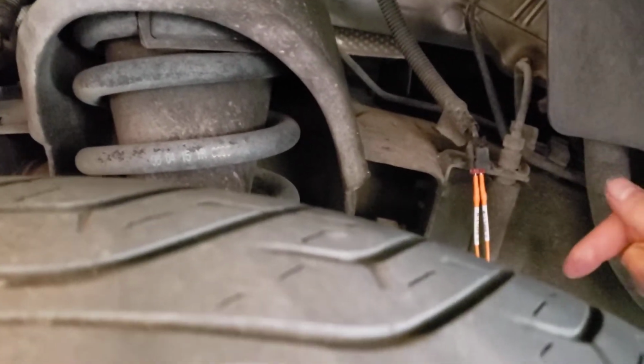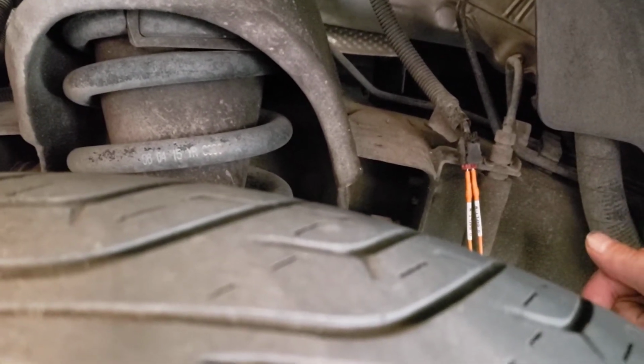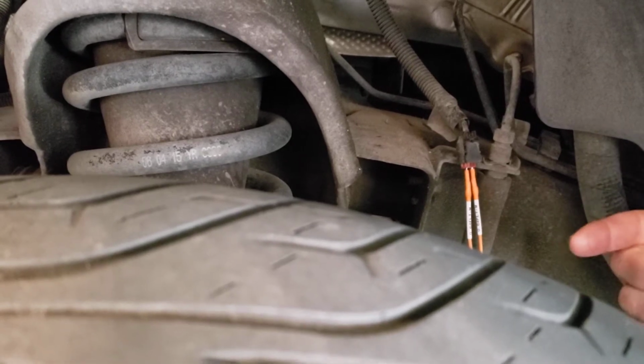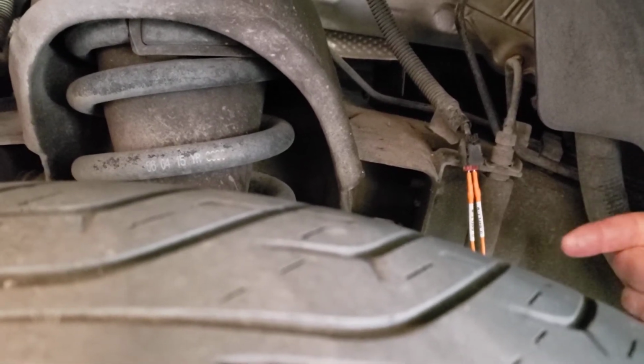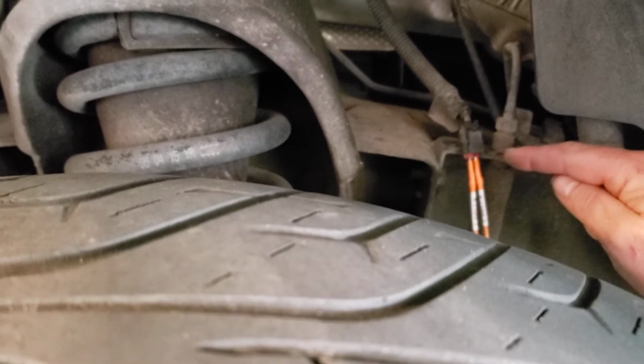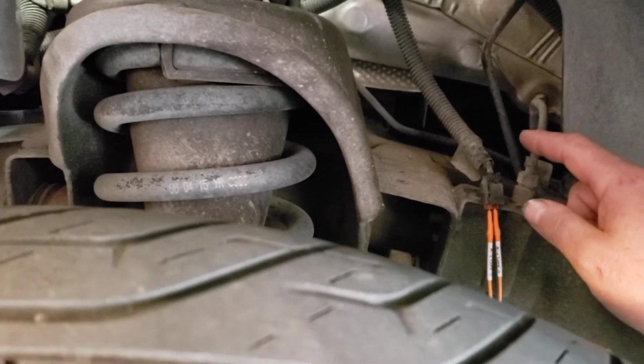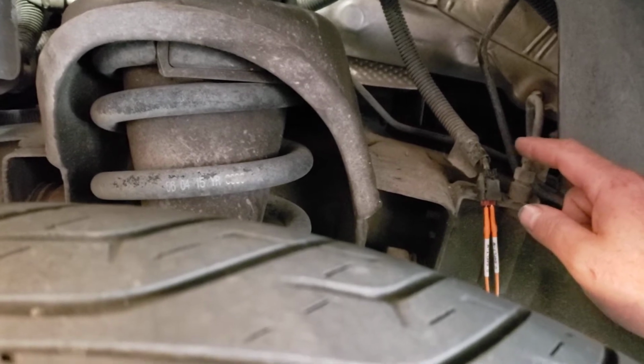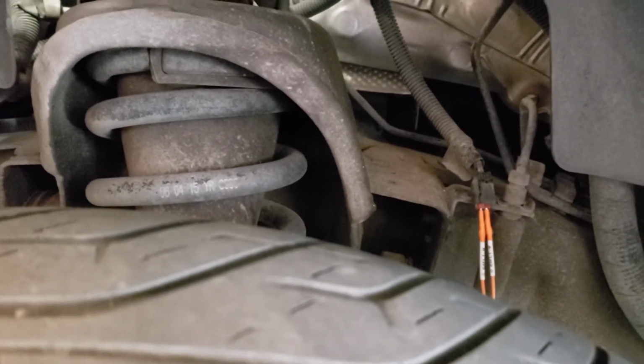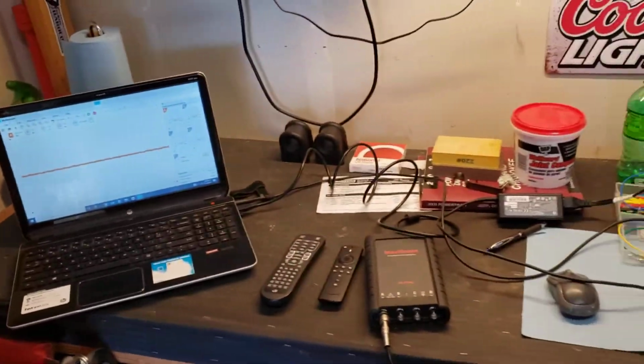Why would you want to use this test? Well, say a suspected bad wheel bearing, say that wasn't the issue, but there's a wiring issue from the connector to the harness through other connectors to the electronic brake control module, we could introduce a signal in there with the function generator and try to troubleshoot that.